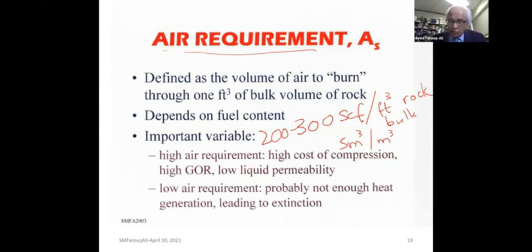A steam generator is a dumb piece of machinery. A big steam generator, typical California, 50 million BTUs per hour will cost you maybe $1.5 million. A compressor, let's say 2 million SCF per day capacity, will cost you perhaps $10 million. And that's a low capacity, in fact.